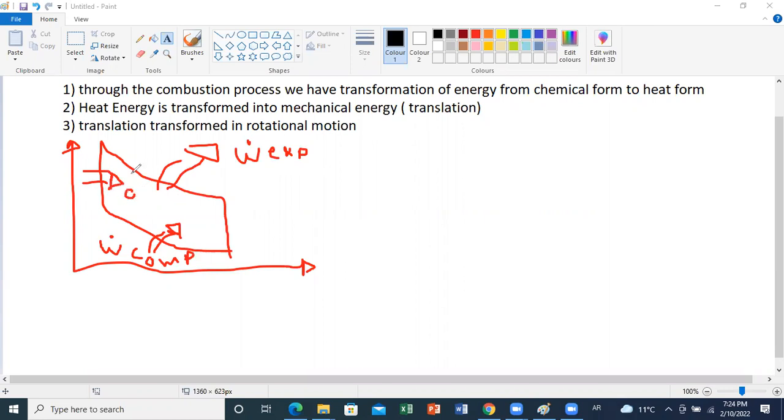So you have Q dot combustion coming in, and because of the exchange processes, admission and exhaust, we can model it as heat rejected during the exhaust phase. Okay, exhaust admission phase. So we have heat rejected. So now, let us say Q1 is the combustion energy, Q2 is the rejected energy.